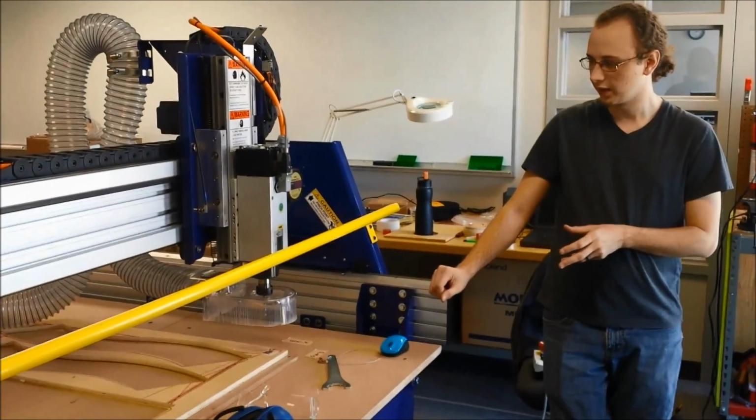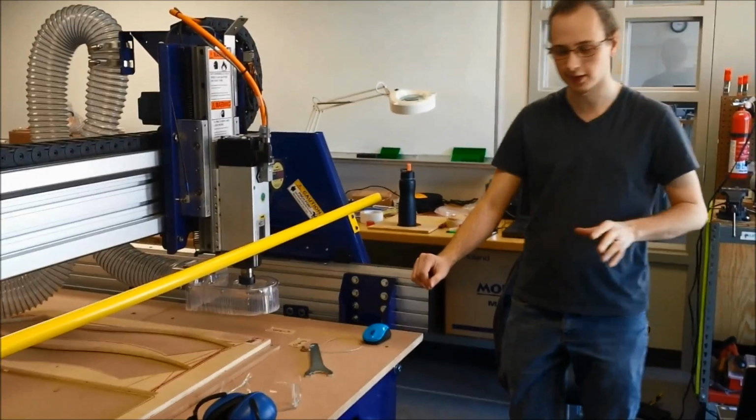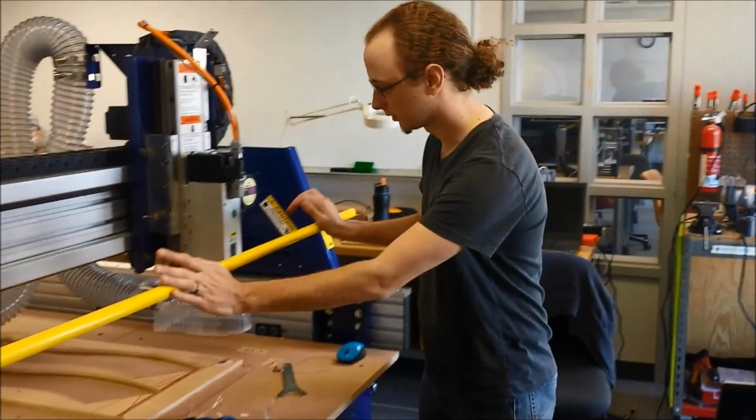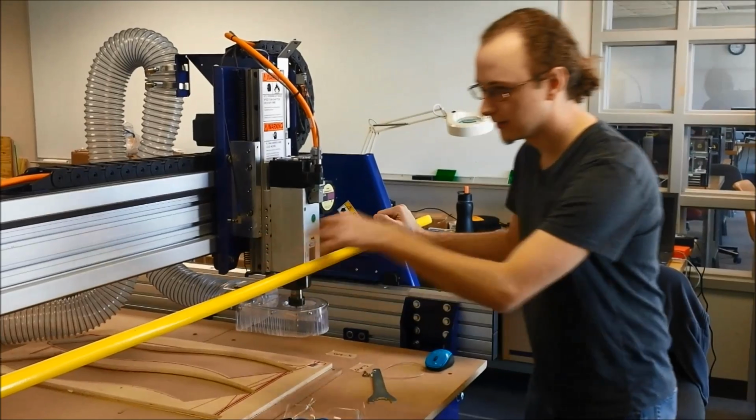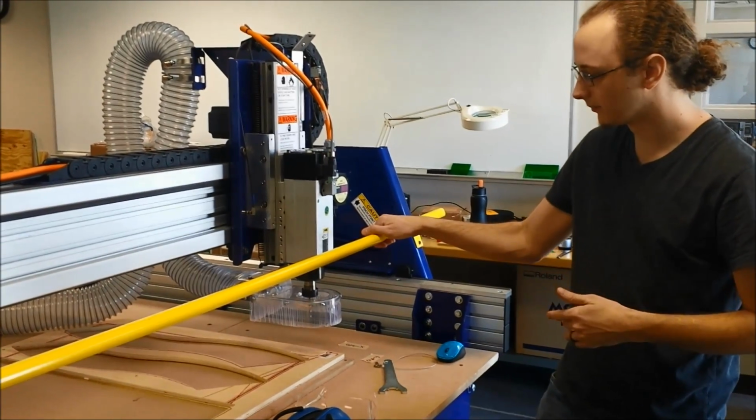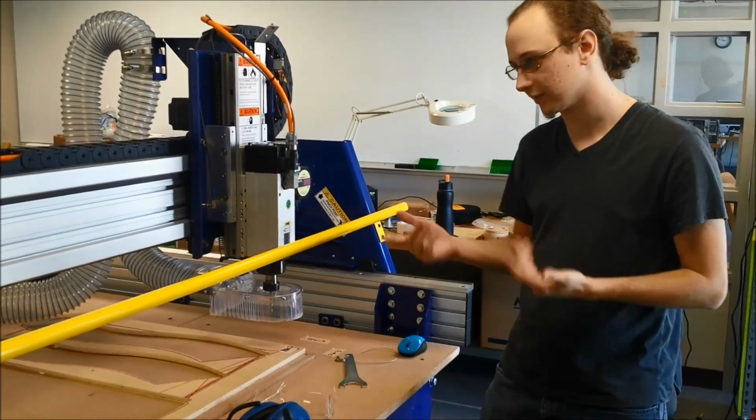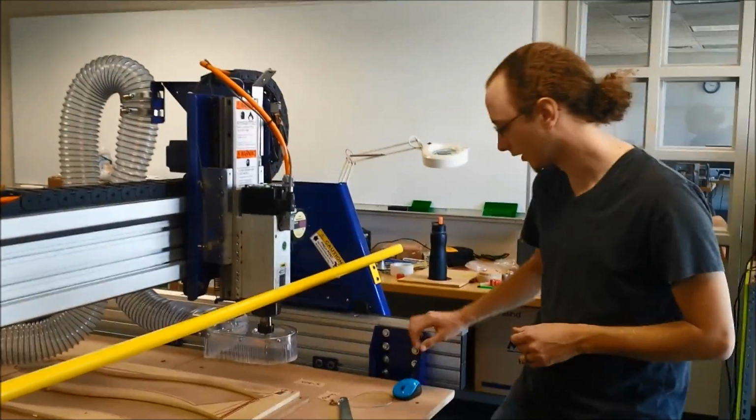But yeah, so mount this on all 4 corners, and when you cut, be sure to have tabs in your pieces so that they don't become free moving whenever they're actually cut out. At this point, the machine has been turned off, everything's off, and so the axes are loose, and we can actually move this if we wanted to, but we can turn it on and drive it, so that's going to be a much better route to go.